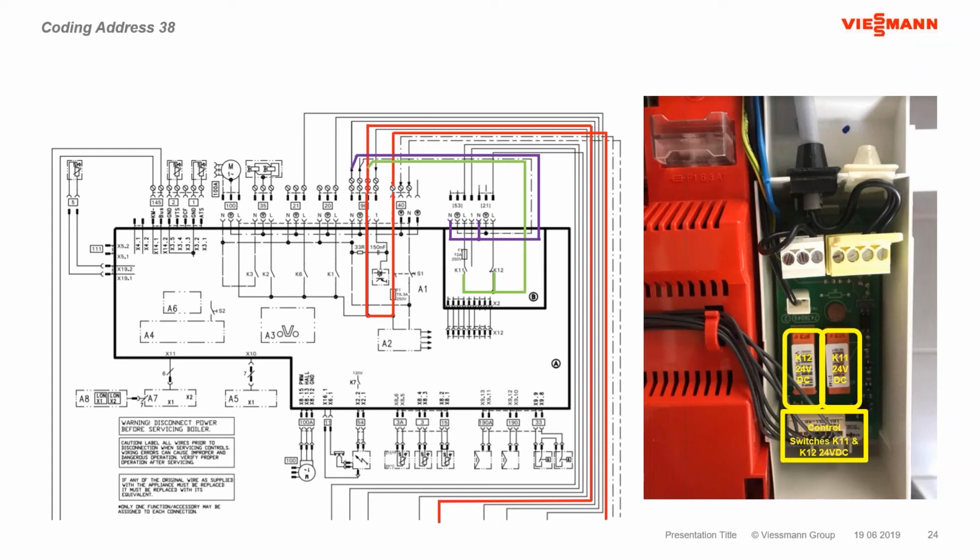It's plugged into an X12 plug in the control console. You'll see it right here, little X12 connection, and we plug in the X2. This feeds, depending on what the call is going to be, the 24-volt DC to close the K11 relay or the K12 relay. So these relays don't close in parallel. They're different functions, so they will close based on the voltage being present on the relay contacts here.